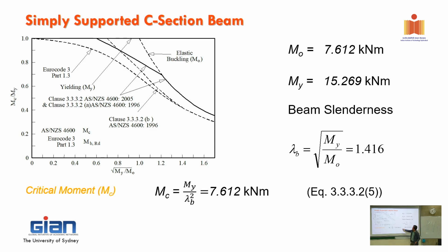Right, so you can see it's a lot lower than 1, probably 40% or something. If you are a designer, this is not a good option, right? That's why in the roof you have to introduce lateral restraint to stop that. Otherwise you have only 40% of the beam because it's subjected to flexural torsional buckling.